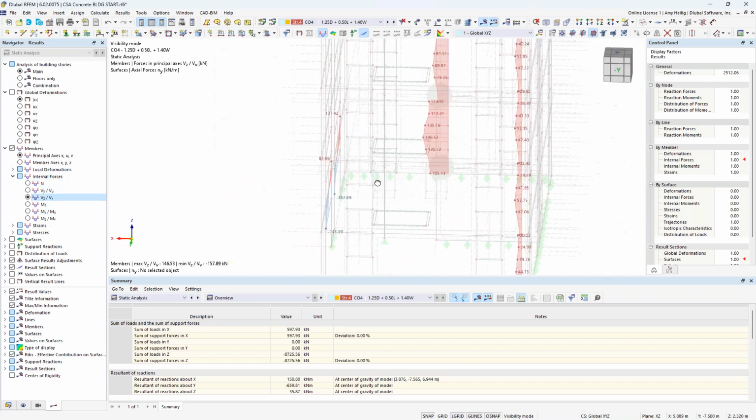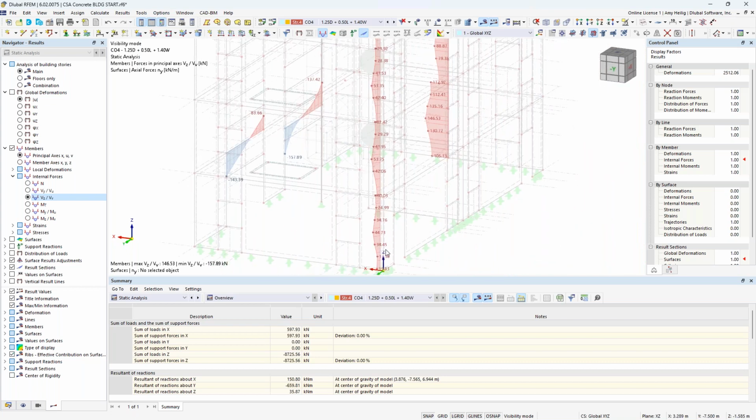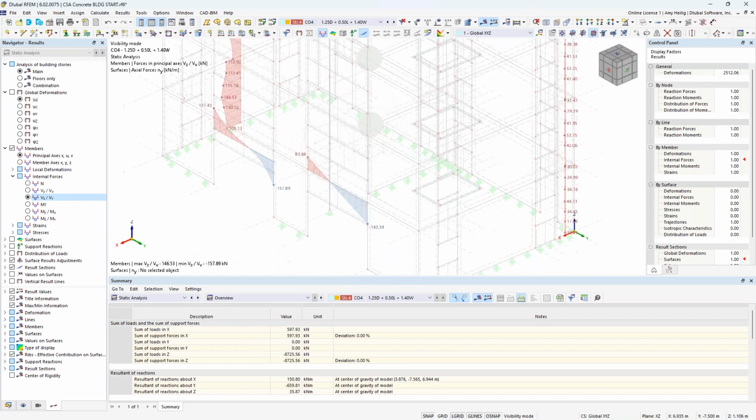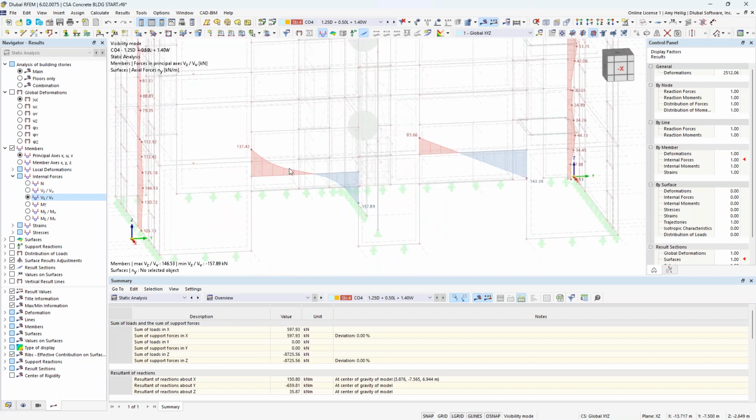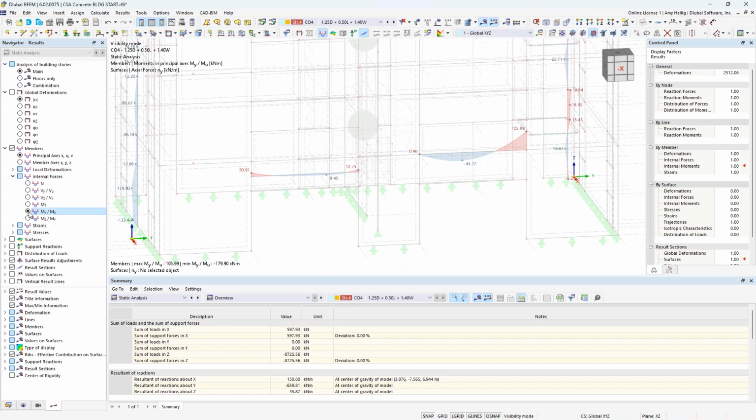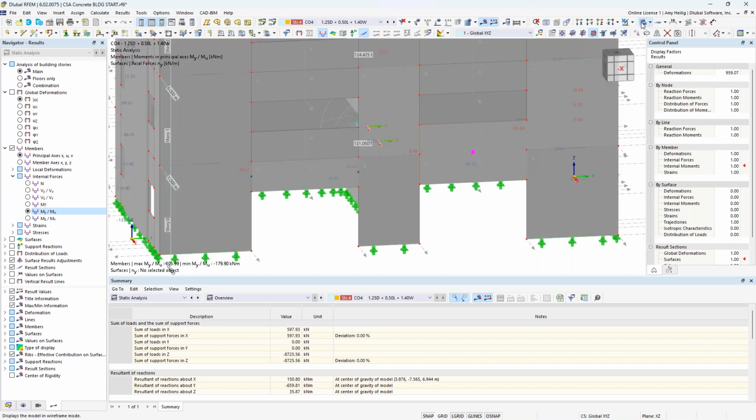And also, remember we had defined those shear walls at the 90-degree angle here at the corner. We still have a result beam that is summing up the internal forces for both of those segments, regardless if they're in the same plane or not. Same concept here for our spandrels. We're summing up the internal forces for this single surface over on the left, but both surfaces are summed up here, represented by a one-dimensional member. We can view information like bending moments. So now with this information, we can take these result beams into the concrete design add-on and actually carry out the design of, let's say, this spandrel as a single 1D member. So if we cancel out the visibility mode here, and I'll turn this into wireframe view, I'll create only a visibility of this single spandrel.